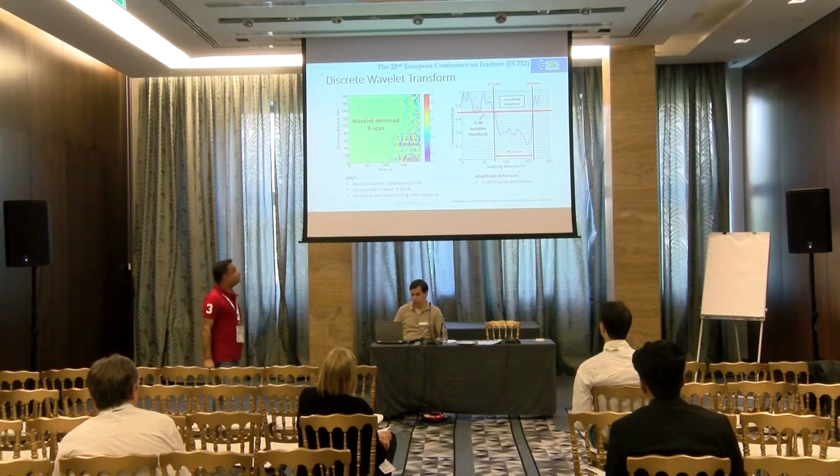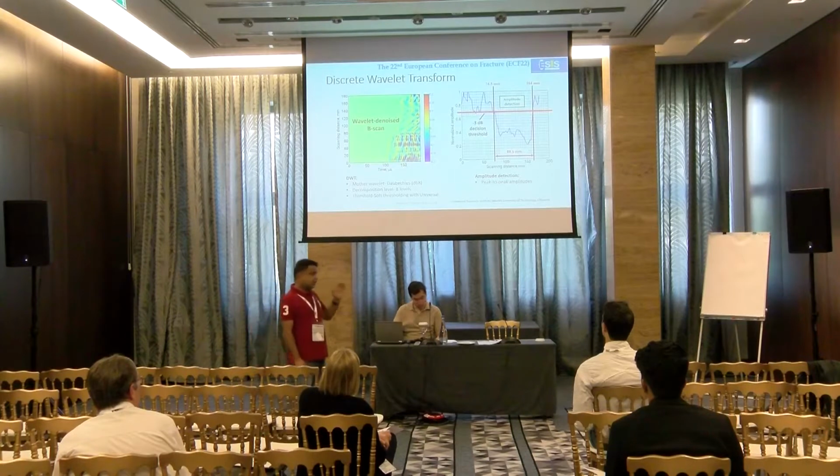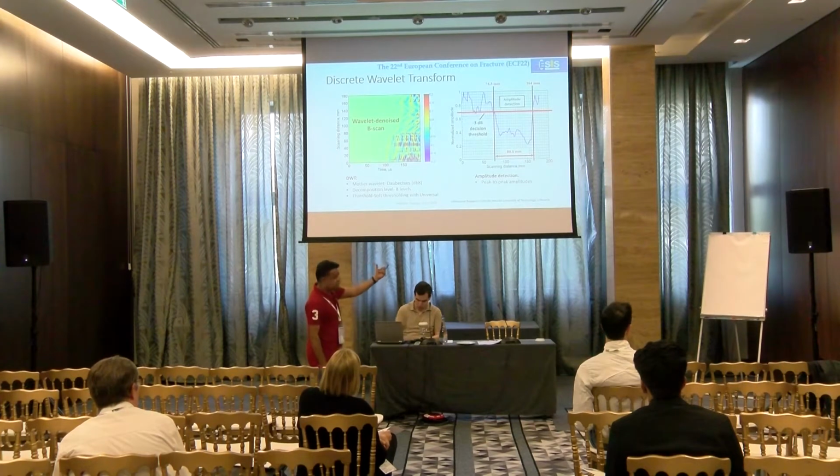You see the size? And the location as well. First location, 74.5. The location on the right-hand side is much more off, of course. So you just happen to pick the left-hand side. The initial location of the defect from the receiving transducer, the starting position of the receiving transducer, is 74.5 mm. And then this is the size of defect.